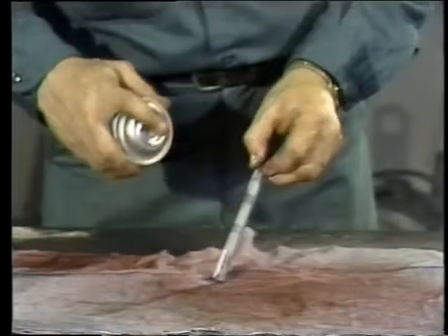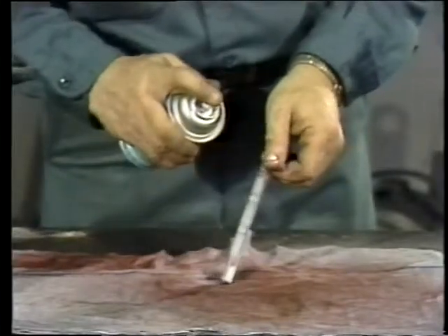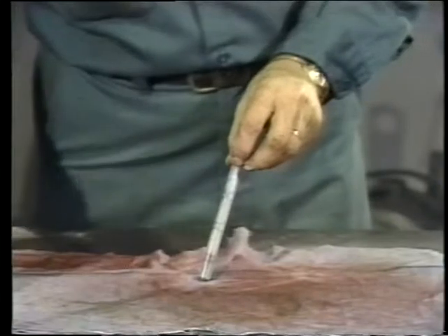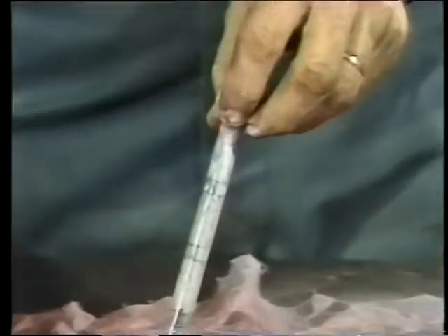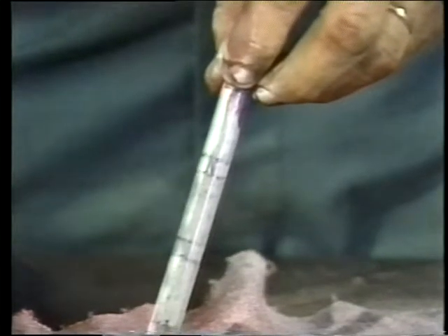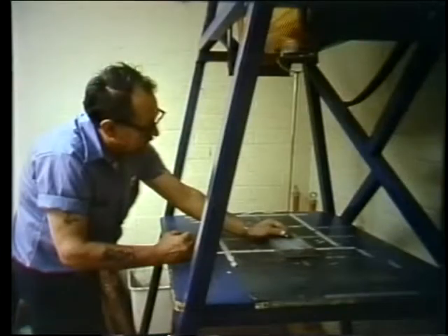Dye penetrant testing will only expose the indication of a possible crack when the flaw is on the surface of the part. So this test is generally used on parts where experience has shown that surface cracking is likely to occur. If an indication of a defect is found, the part may be tested again with another method to define the nature of the flaw.